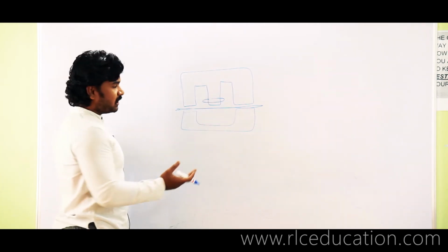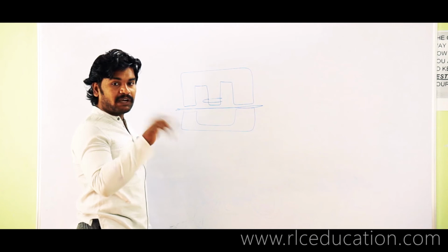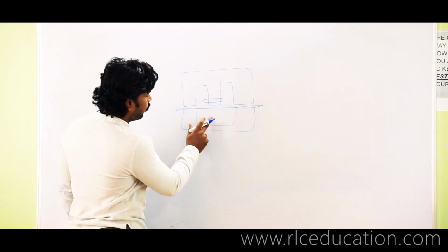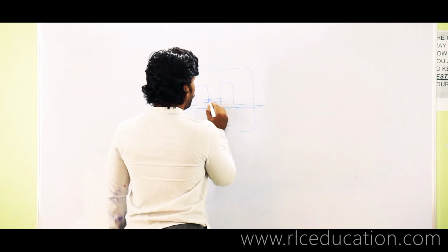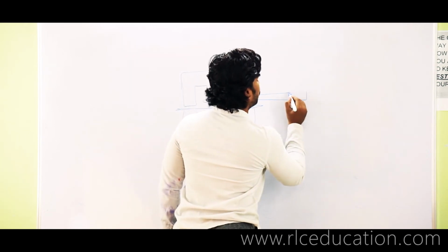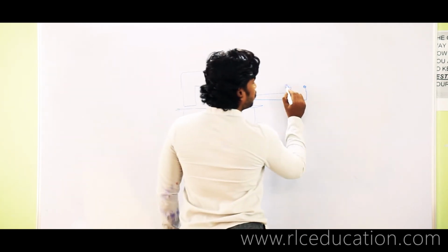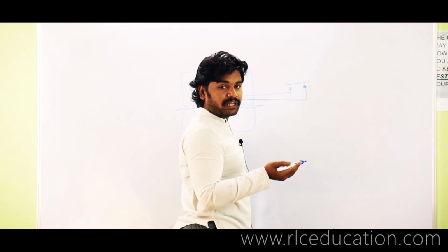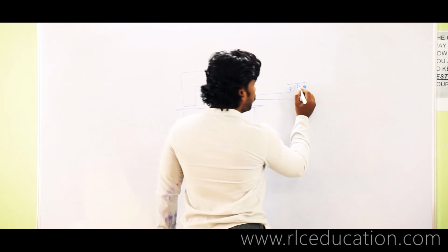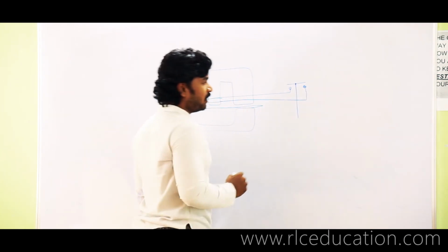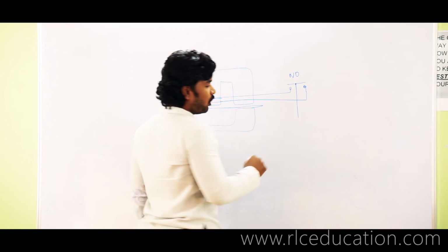So we are going to utilize this weakness of the directional element to solve our purpose. What is our purpose? We want the overcurrent element to operate only if the directional element says okay. So I will take the shading band contacts outside, and create a condition that these shading band contacts will be closed only if the directional property is satisfied. For example, let us say this is a normal open contact. The shading band or shading coil contacts are normal open contacts.